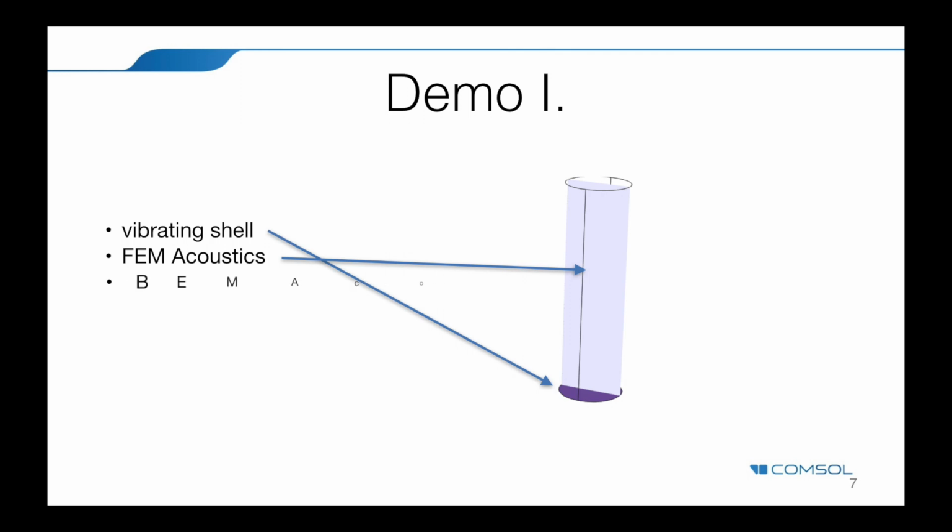And we will also add the boundary element method acoustics physics interface, and we will couple it to the other two physics to set up another calculation, so we can visualize and calculate the sound pressure level and the acoustic pressure outside the physical domain anywhere without any limitation. So that's a new feature. We can create hybrid models coupling the finite element acoustics to boundary element acoustics.